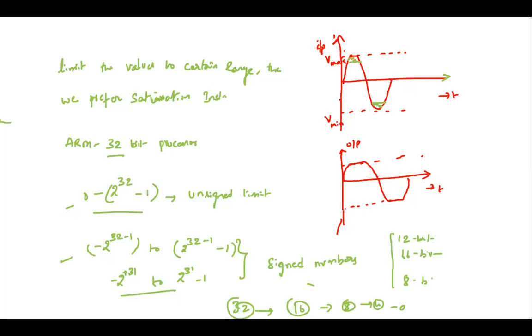We have another flag called the Q flag. The saturation programs that we are looking into all deal with the Q flag. Q is nothing but saturation; sometimes it's also referred to as overflow. Saturation instructions deal with the Q flag, moving data from the registers to the flags, and from the flags to the registers.